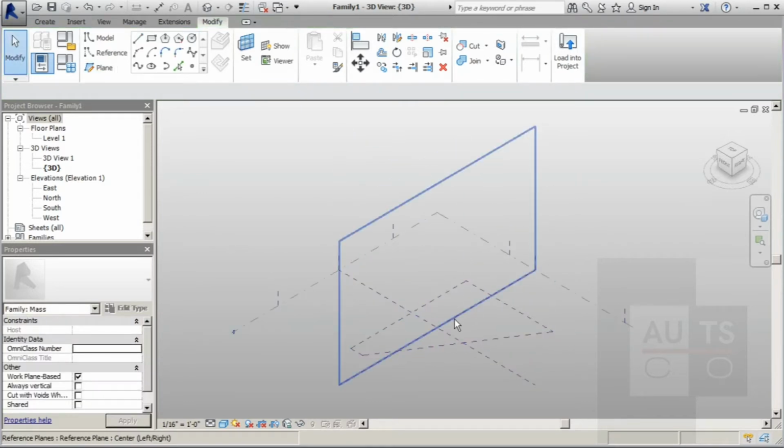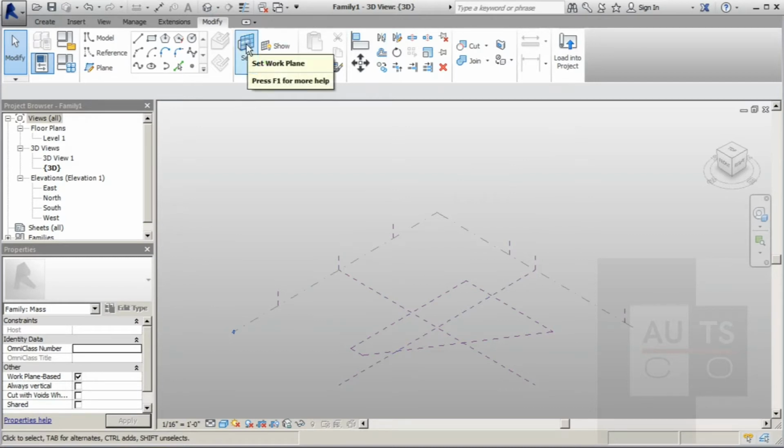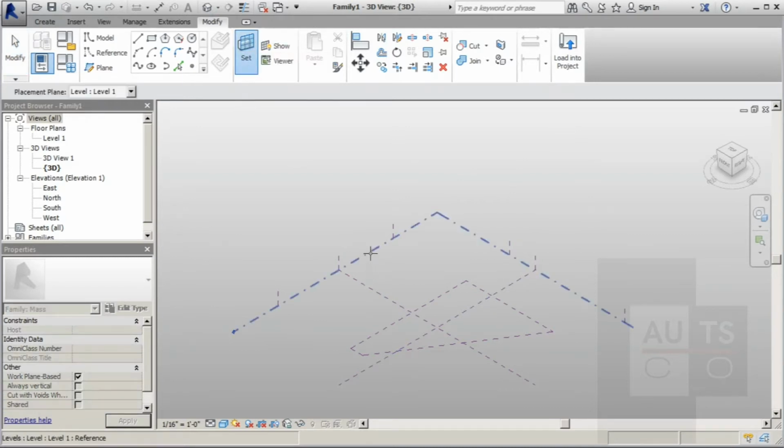So if I wanted to, I could select all these and create a simple surface, but I don't want to create a simple surface. I want this to have a nice, elegant curve to it and a sweeping look. So to do that, we're going to set some reference points, and also we're going to be working with some splines. And I'm going to show you some really cool ways to create forms other than just using your basic extrusions or sweeps. So we're going to start working with some of our reference points.